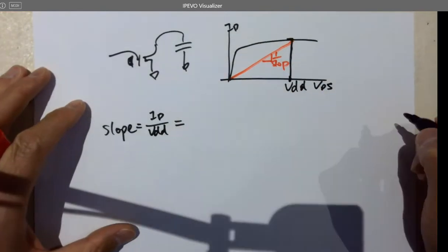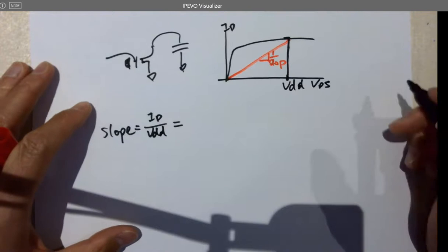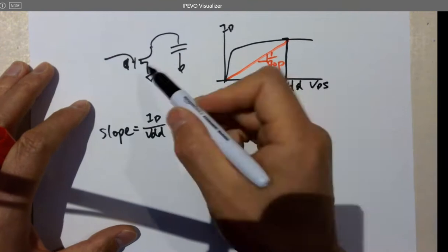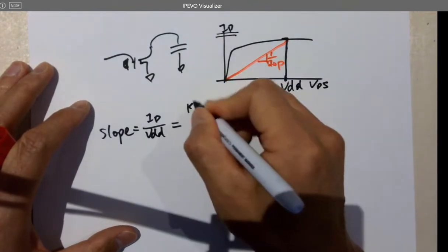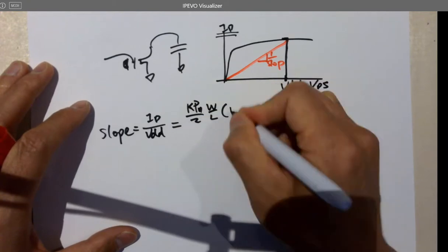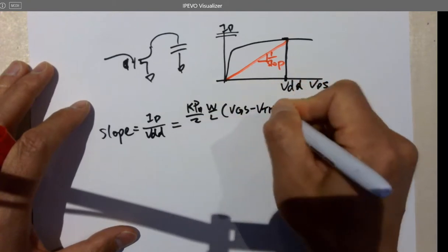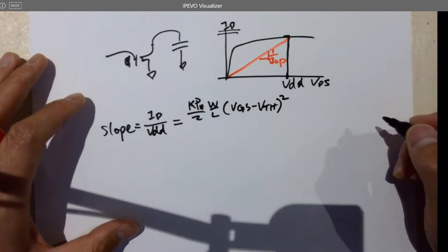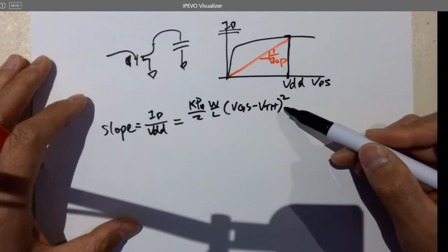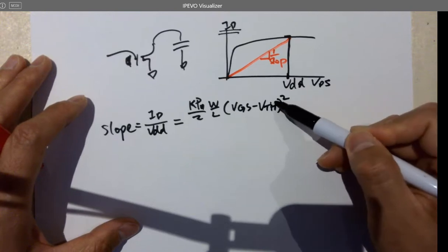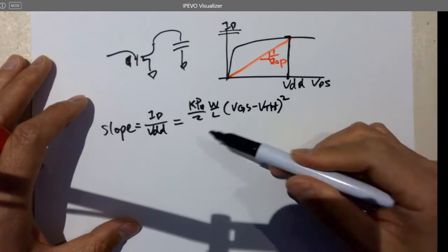I forgot if I covered it in logic, but you should know that for NMOS, the way to calculate IDS is this square law equation. That's ID. We're not going to use this to calculate currents in this class. This is usually microelectronics 2. You have to calculate the current and find the VGS for DC analysis, and then gm for AC analysis.